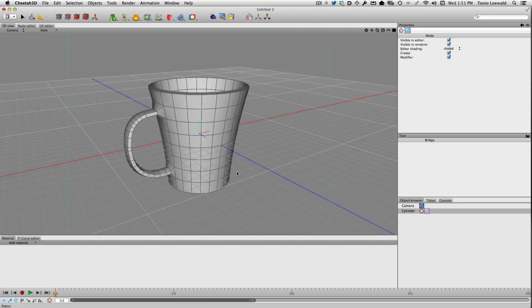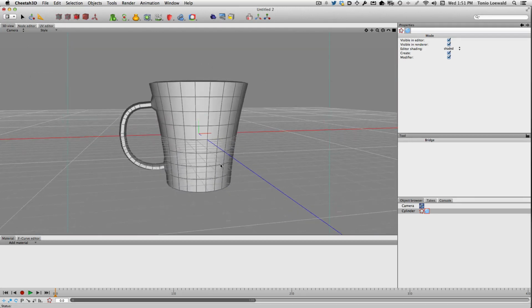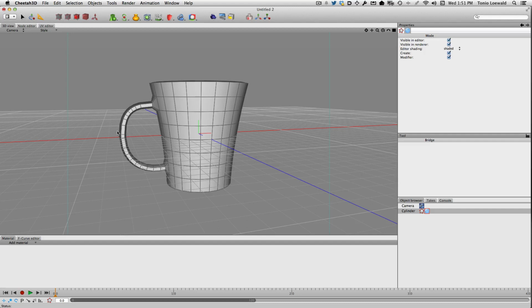Okay, now I'm going to refine the mesh by making it a bit smoother. Now I should let you know that I've actually changed the setting. So remember how I collapsed this thing with a 20-degree approximation angle? Well, it looked kind of ugly. So I went undo, undo, undo, undo. I went back, I changed it to 10 degrees, and then I redid the steps that I had to replicate. It's an example of the point of no return coming to bite you. So this is a 10-degree handle, not a 20-degree handle, but never mind.